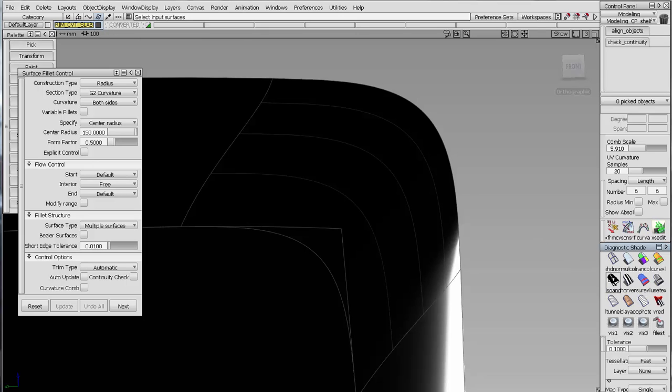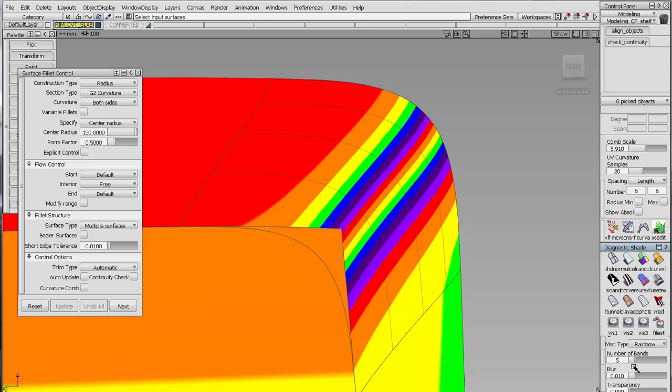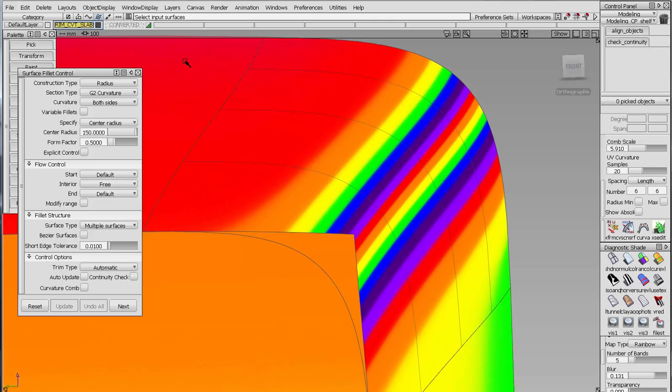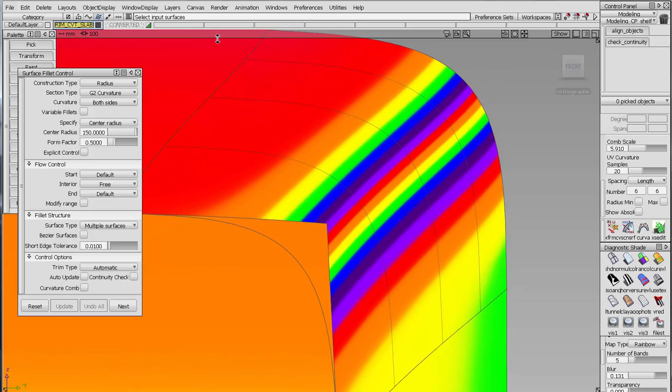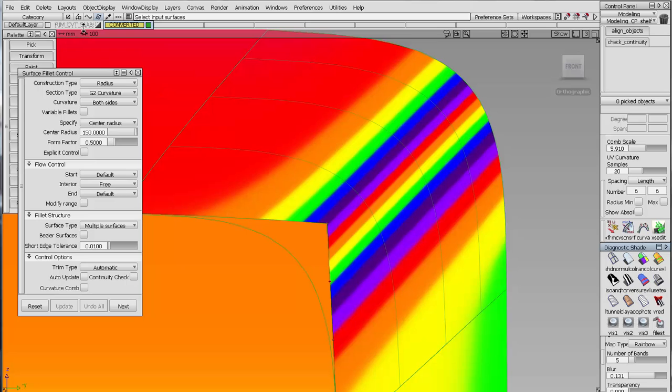So I'm going to turn on my ISO angle tool and set it to multiple rainbow, maybe this many bands, and I like about just some blur, maybe 0.1 blur. Just softens it a little so you're not too crude, too picky. And if we look at this in the front view, and now we switch between the two and switch this to ISO angle, now by toggling you can see the difference.